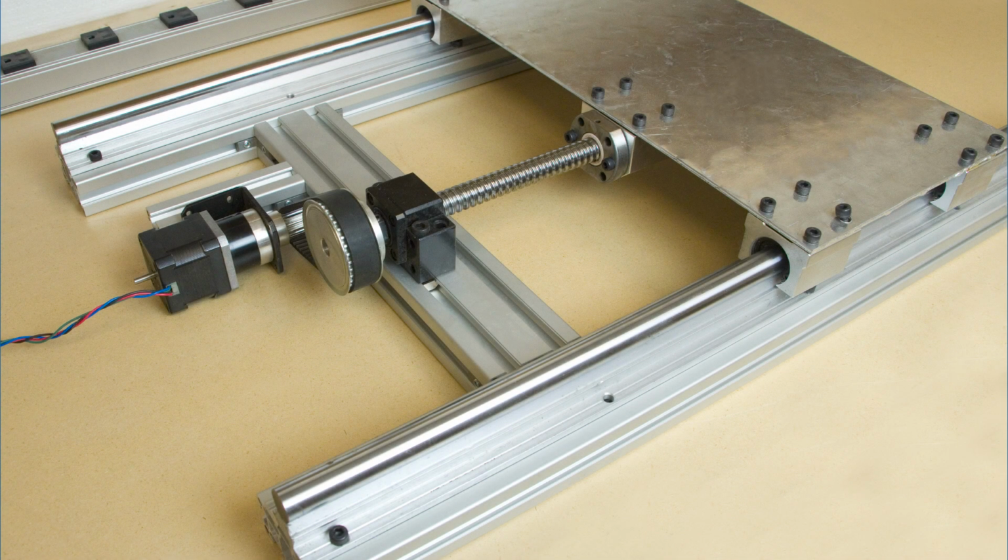Here we have a linear motion assembly, driven by a stepper motor. The motor drives a pulley connected to a ball screw that converts the rotation into linear movement. We can set a rescale factor that reflects the movement of the platform in millimeters. In situations like these, the rescale factor must be calculated manually.